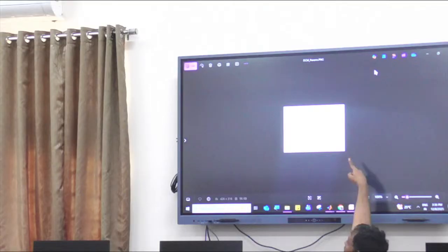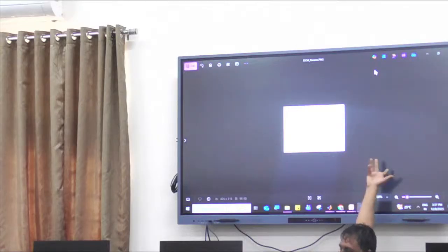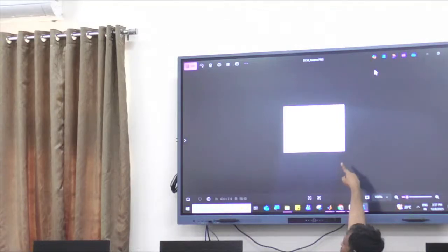So my inertia, the J value, I want to keep it 0.01. My motor friction, I want to keep it as 0.1. My conversion constant, you can see normally both the KE and KT will be the same, so I have simplified it and made it as K value, which will be 0.01 once again. And my motor resistance, we are expecting it to be 1 ohm, negligible internal resistance of the coil. And the motor inductance, the coil inductance, we want to update it as 0.5 henries. So these are the values we want to perform the simulation with.